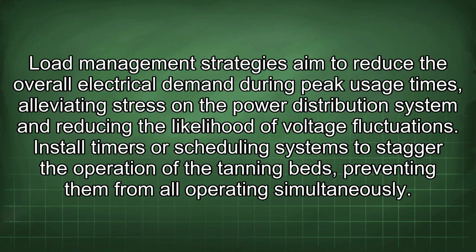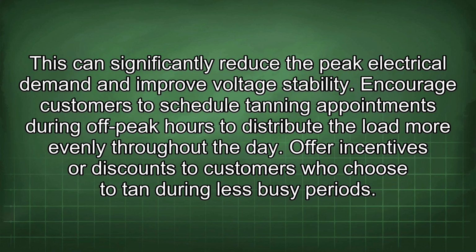Load management strategies aim to reduce the overall electrical demand during peak usage times, alleviating stress on the power distribution system and reducing the likelihood of voltage fluctuations. Install timers or scheduling systems to stagger the operation of the tanning beds, preventing them from all operating simultaneously. This can significantly reduce the peak electrical demand and improve voltage stability. Encourage customers to schedule tanning appointments during off-peak hours to distribute the load more evenly throughout the day.